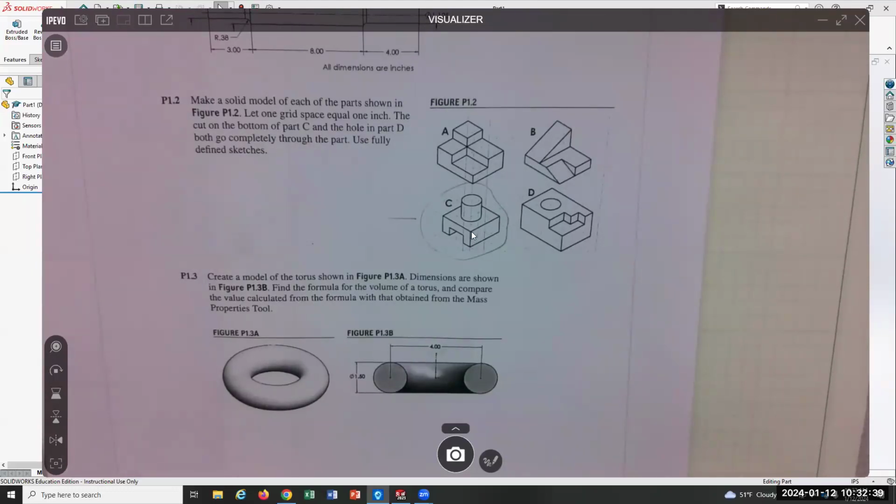So modeling intent, I would probably model this surface first, right? With that notch out, and then I would extrude it this deep. Again, this is the front view. We want to kind of keep that in position so our object's in the same position as the object we're trying to model.